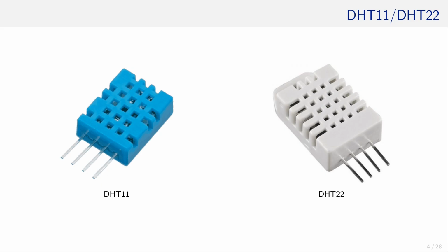The myth is that the DHTs utilize the one-wire communication protocol. Though there are similarities when the DHT11 or DHT22 communication protocol is compared to the one-wire protocol, they are not compatible and have major differences. We are going to talk about those differences in this chapter.